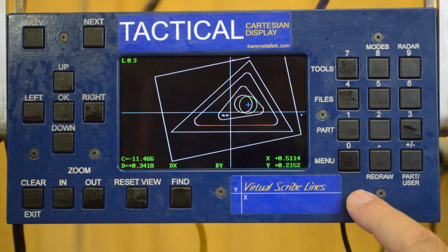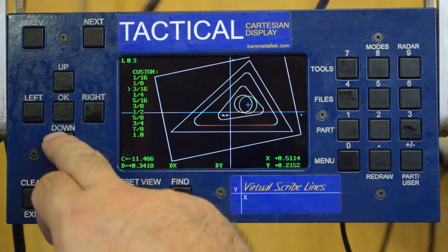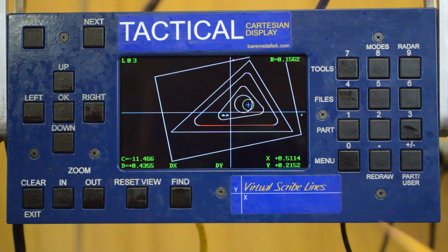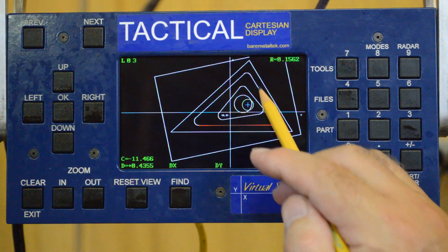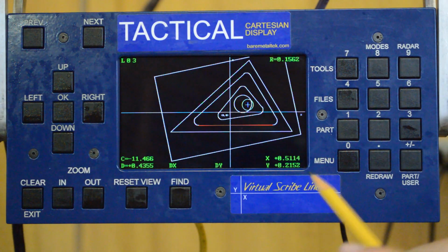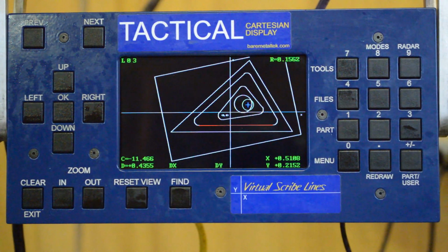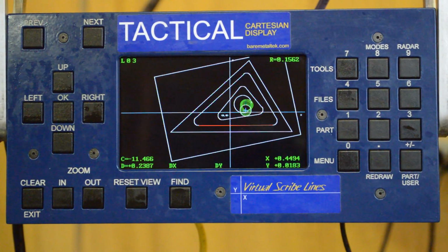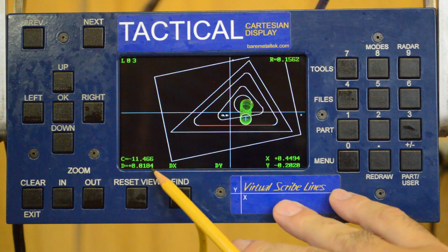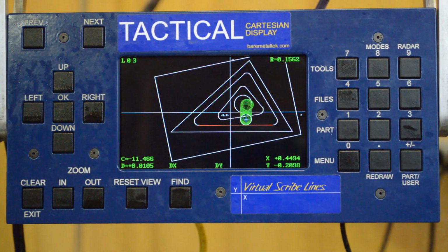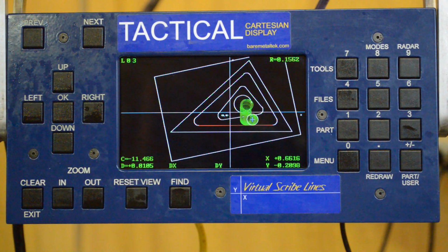All right, now I'm going to switch the tool to a 5/16 end mill, and I'm going to use that tool to semi-finish this interior triangle. There's still a lot of meat in these corners. So now I'm going to leave 10/1000ths of stock on each one of these walls. So I'm going to get down to within about 10 here. All right, close enough. Now I'm going to feed into this wall.